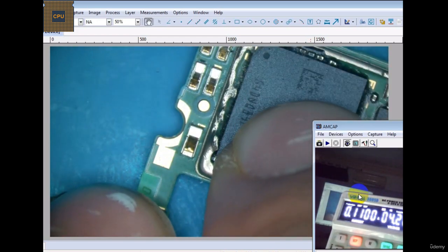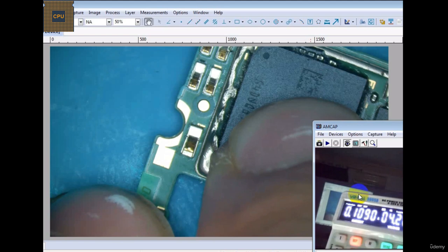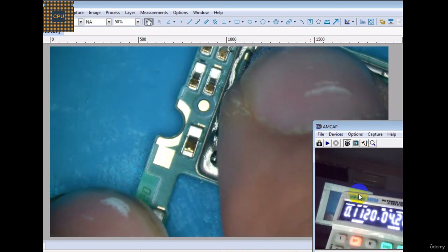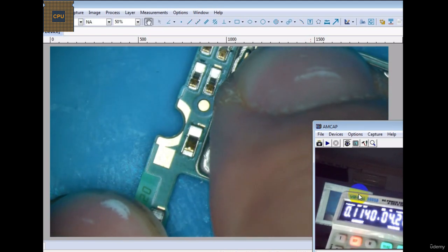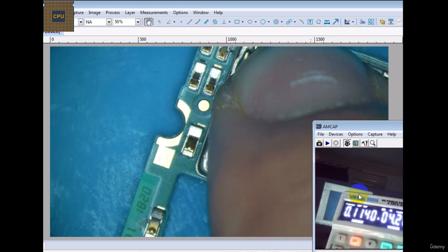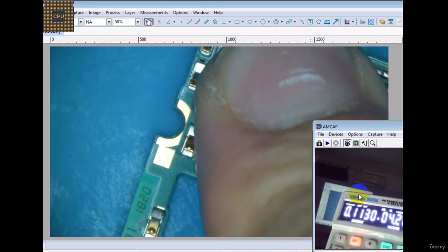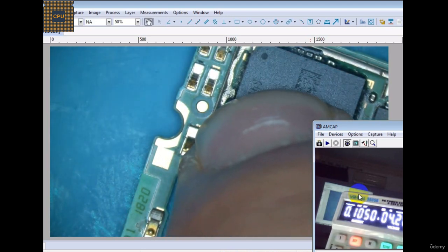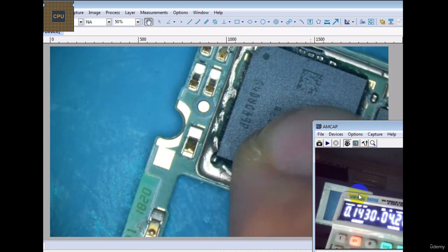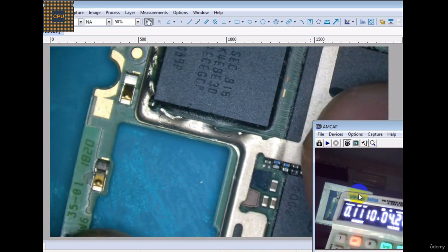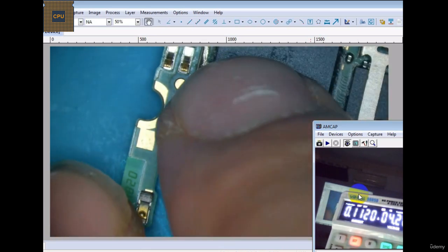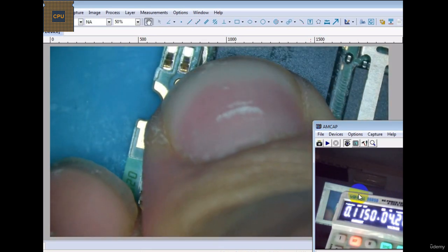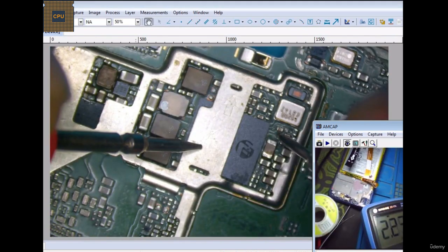So in the next step, we will press on the IC. Maybe the phone took a damage or something happened to the phone itself, so we are going to press on the ICs, like the 3 ICs that we mentioned before, and keep your eye on the power supply itself. If the power supply goes more than 0.1, this means that this IC is a problem. We are going to press on all ICs, but just a light pressing. Don't press so hard.